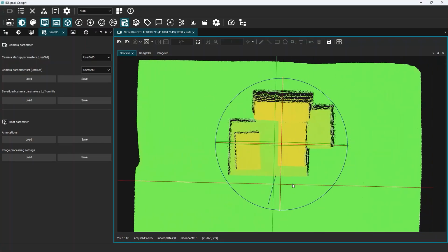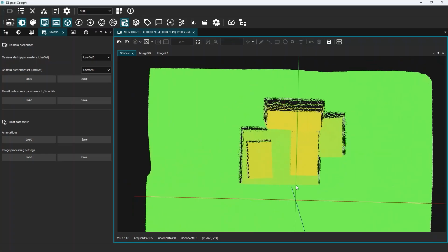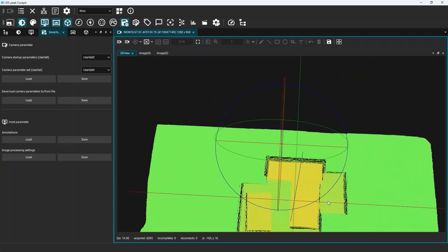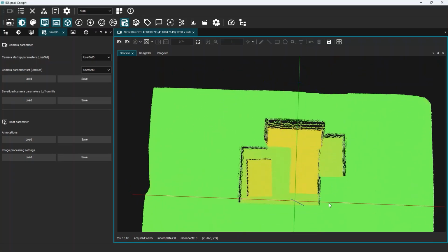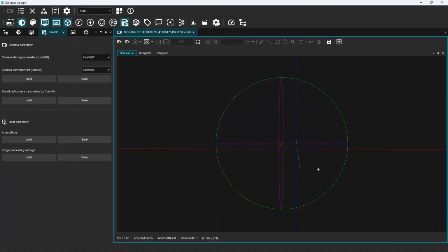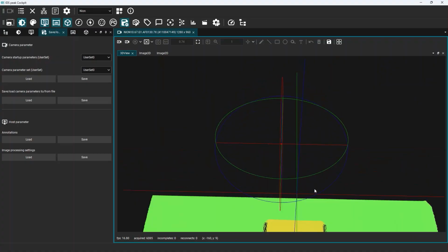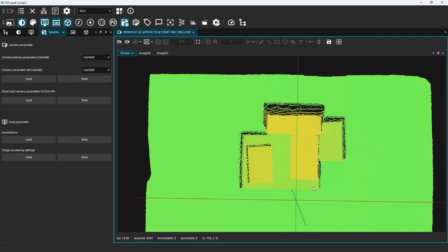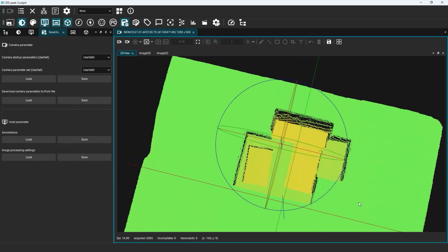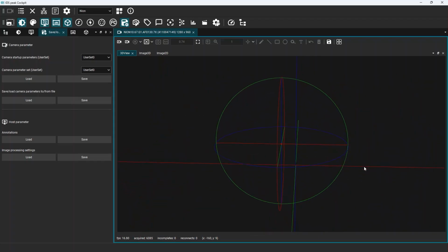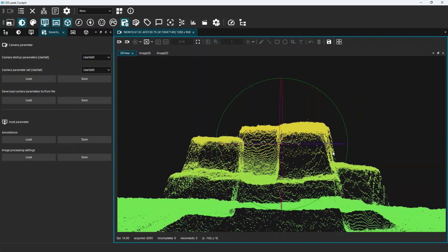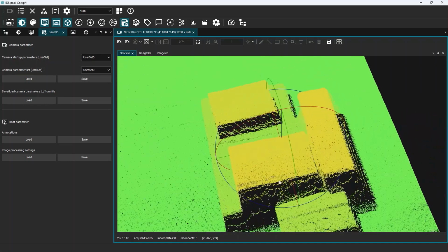At the moment, the origin of the data, the zero distance, is at the camera. This is indicated by the red, green, blue cross. When we rotate or pan around the point cloud, there is another red, green, blue cross, this time within a sphere. This, by default, is at the point cloud origin, but by shifting the point cloud, we can adjust this sphere to center around a plane or specific object in the point cloud, making it a bit easier to manipulate.